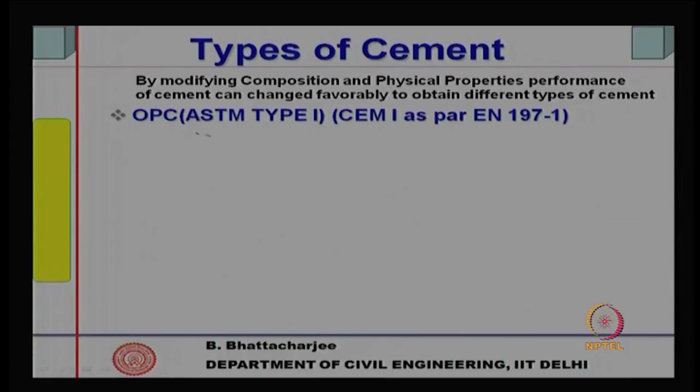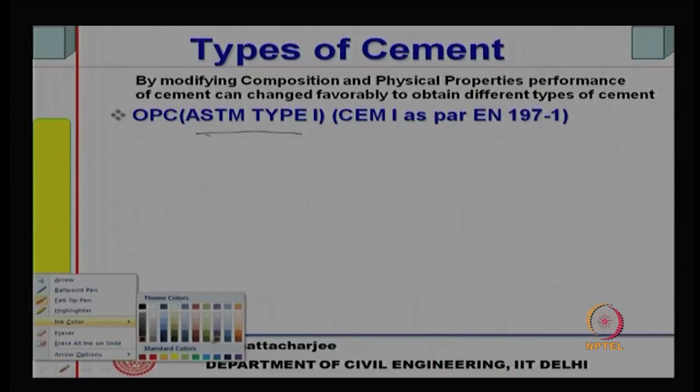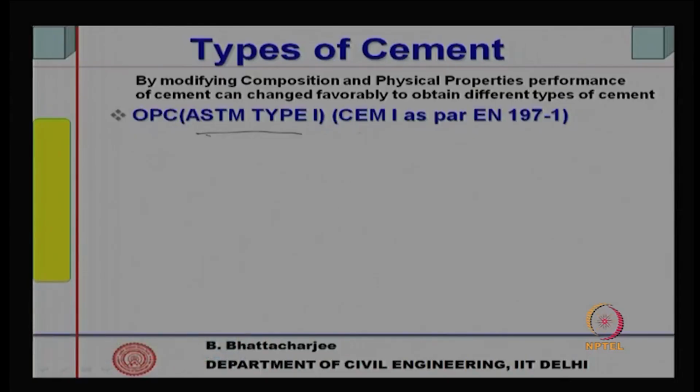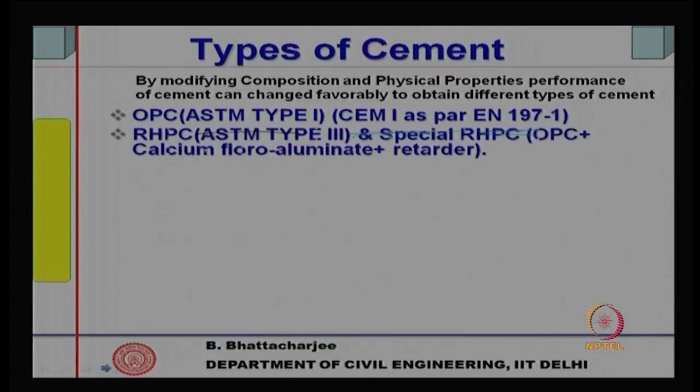ASTM of course classifies OPC as type 1, and CEM 1 is what EN 197-1 says, that is the European standard, right. BS standard also used to call it that, but now all European codes are integrated, and this is CEM 1 as per European standard.